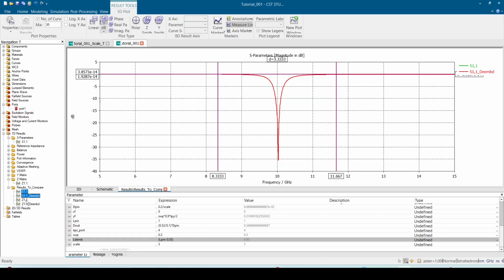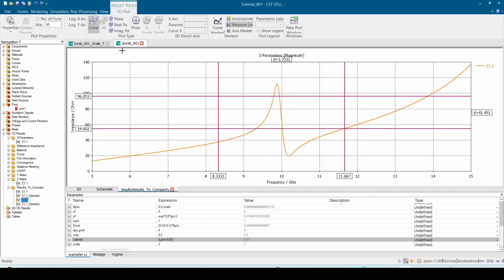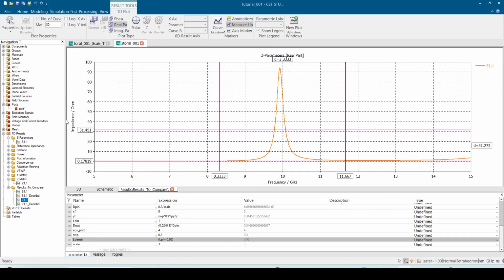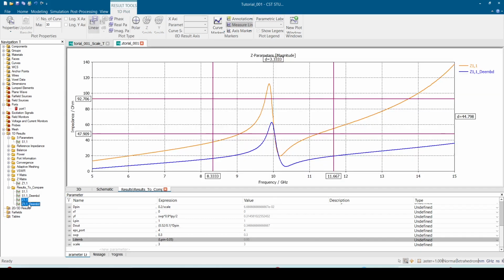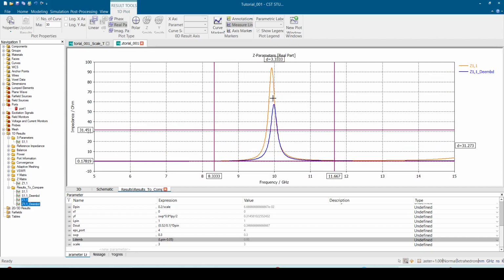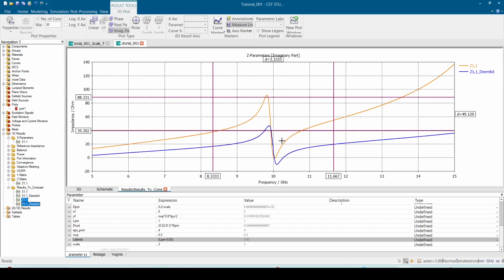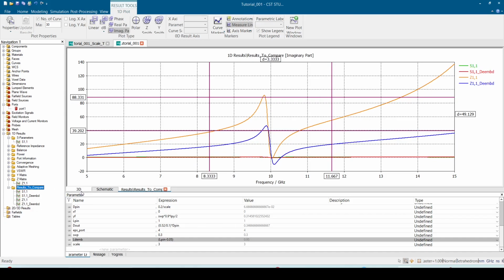The same for the Z parameter, it does not have to be literally the same. If you look at the real part, it is not literally the same. So when I do the de-embedding, I see a different real part, right? It means that it was this value, and then when I do the transmission line and move the distance, it starts to go up, large, and down, large, because we also have an imaginary part. So that's why I'm saying the best thing is that you de-embed, right?